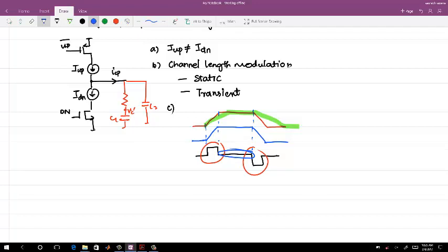On an average, if you look at one reference cycle, it is zero. So the V control will not change. The DC of the V control you can maintain at zero in a locked state, but you will still have the transient injection current pumped into the loop filter, and this will cause the reference spurs.